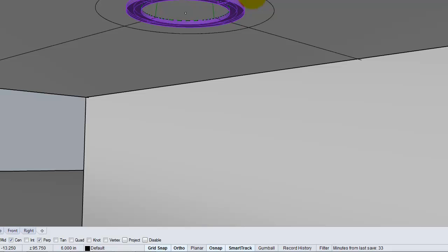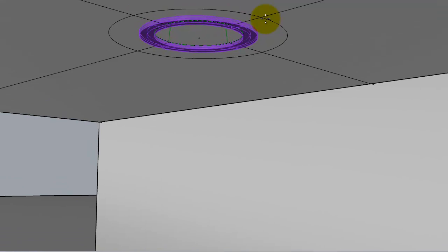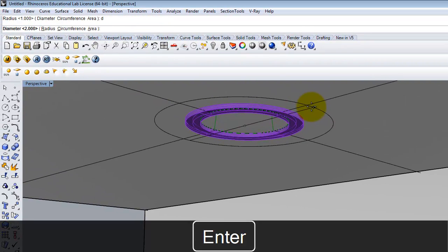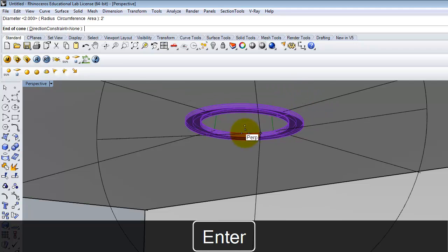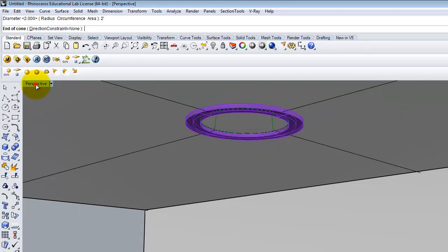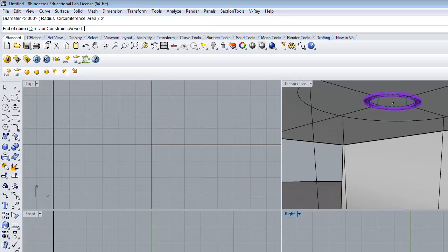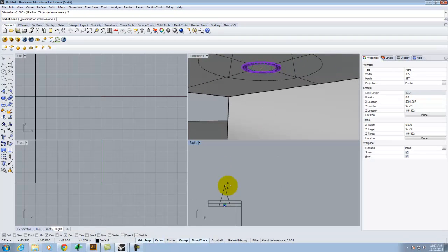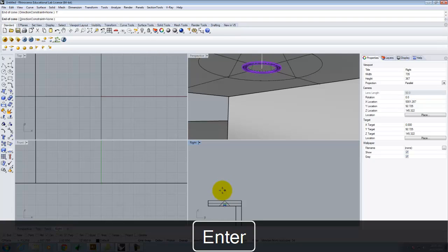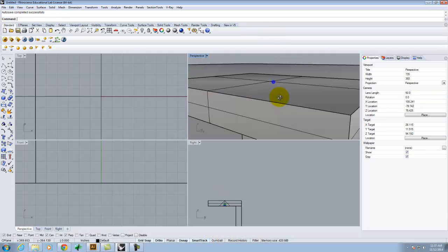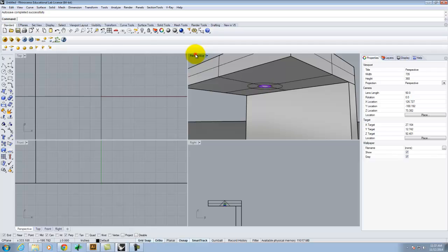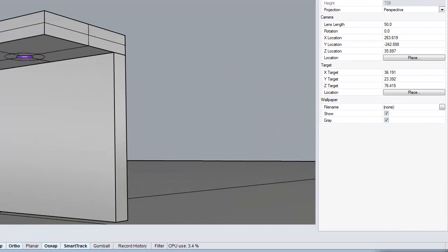And so there are a bunch of notes under item 4 for how you create this spotlight. Okay, what I'm going to do is I'm going to say the base should be about 2 feet. So I'm going to press D for diameter, and then I'll say 2 feet. Right, and then I want the height to be 1 foot. So I'm looking for a 2-to-1 ratio in this. Okay, and that's just from practice. I think it tends to work out pretty well. So I switch my view into the right view, and I type 1 foot here, and it builds a cone for me.